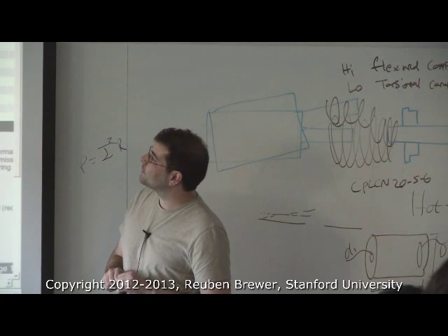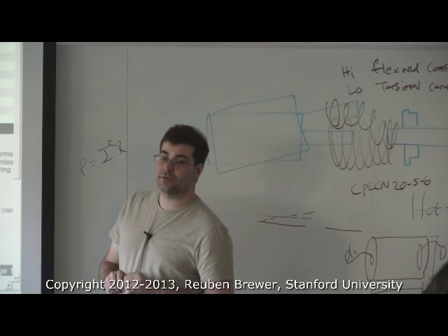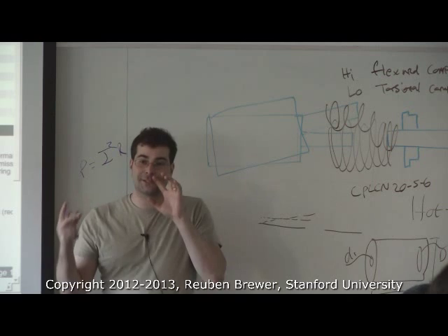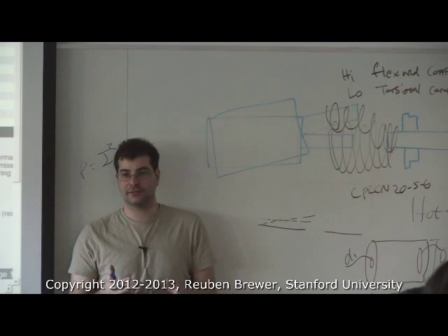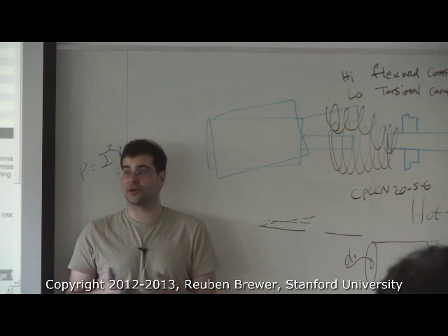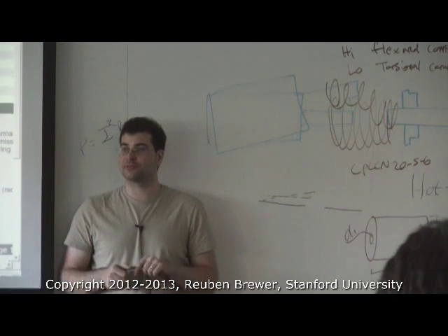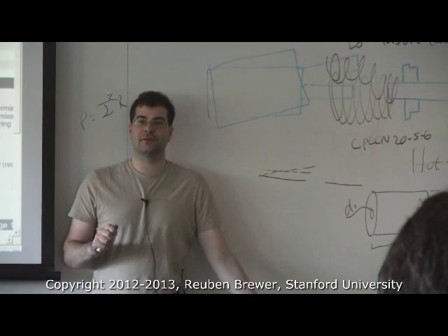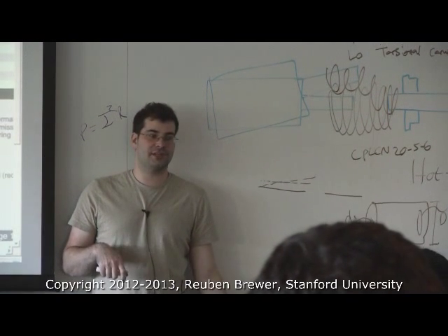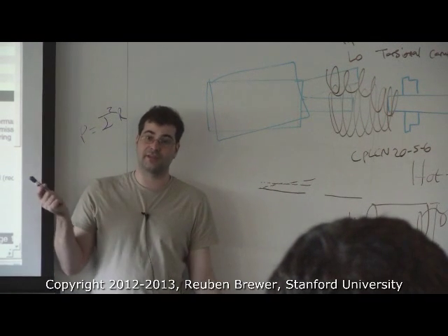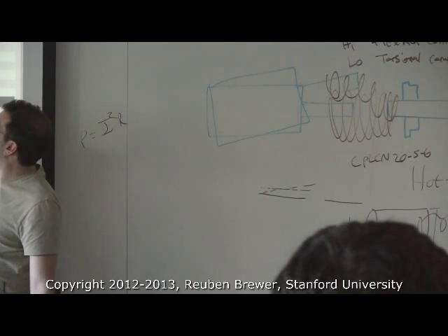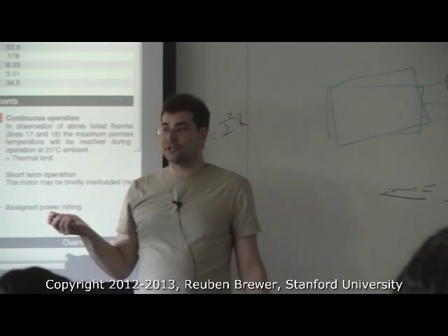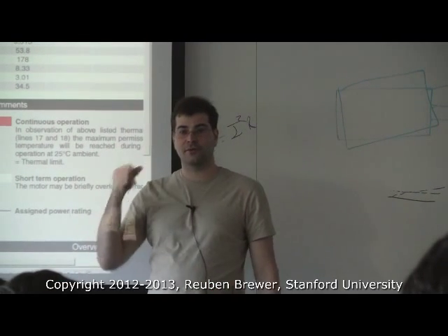So it's the same motor? Same motor, yeah. Maxon is assuming that your motor is in air, as most motors are, and that's a pretty safe assumption. But just know there are some special circumstances where, if you're doing underwater robotics, all of this would change. What you need to know as a takeaway from today is stall torque can only be used for the duration of turning on your motor.